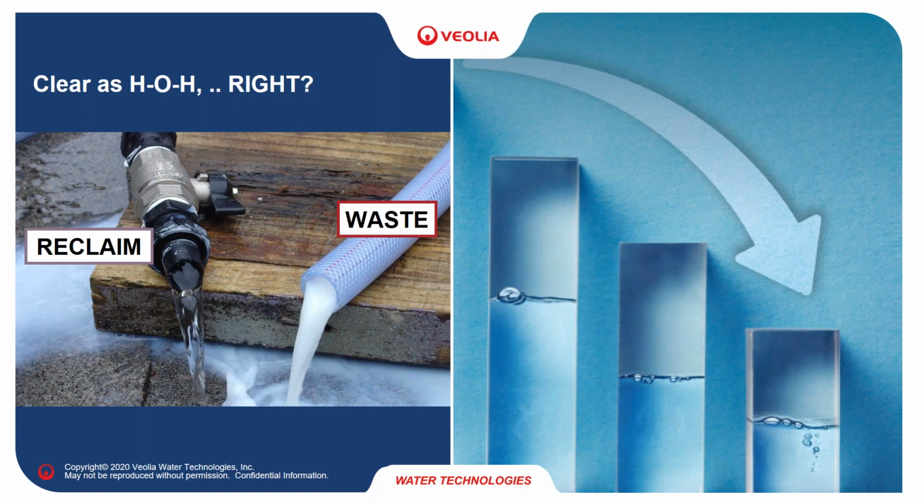As far as the mobile water clarifier itself goes, Veolia does have a fleet of mobile trailer-mounted upflow sand ballasted clarifiers, the ActiFlow technology, that find application in situations like that. And the ActiFlow mobile units can handle flows up to 1,100, 1,200 GPM for larger trial type situations and applications.